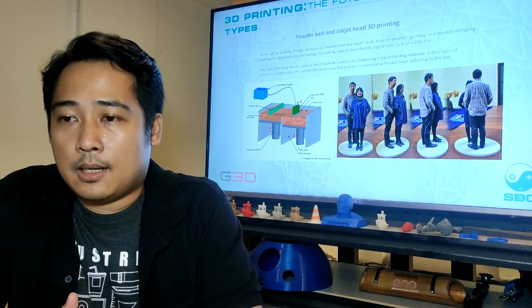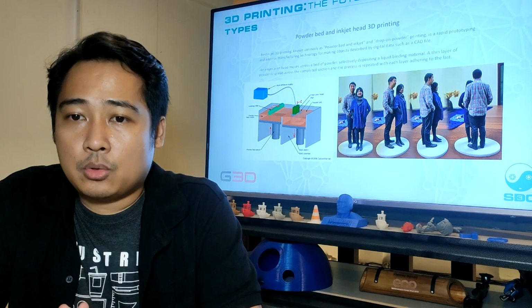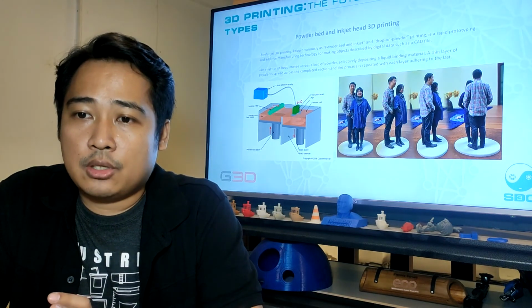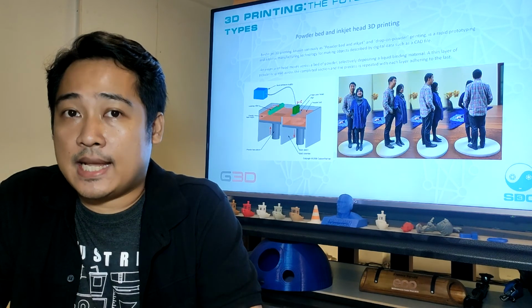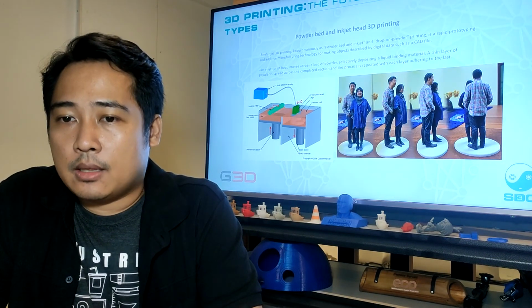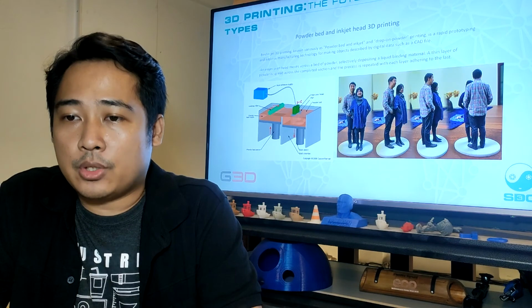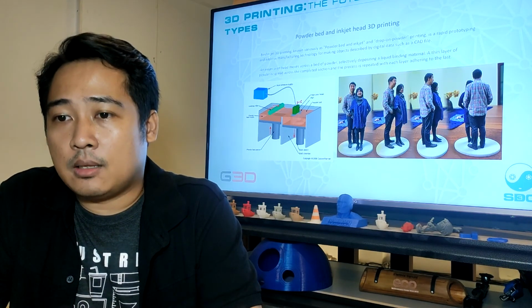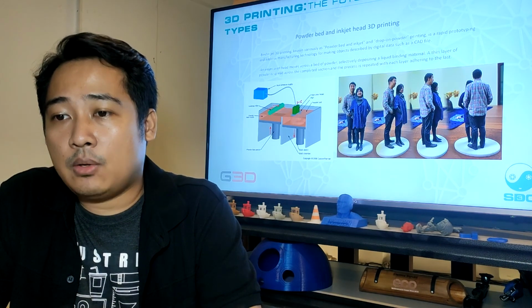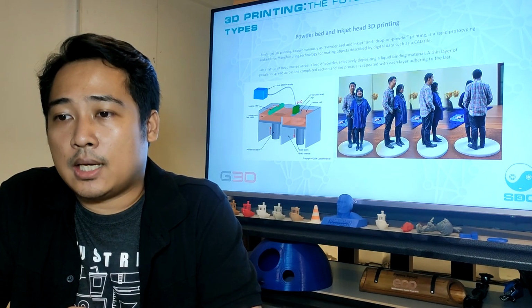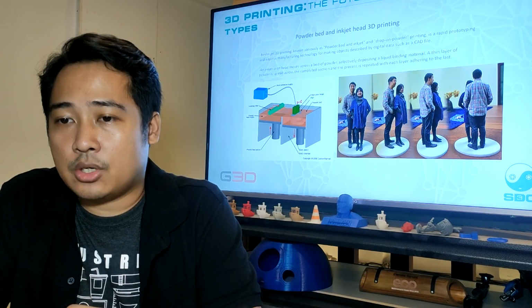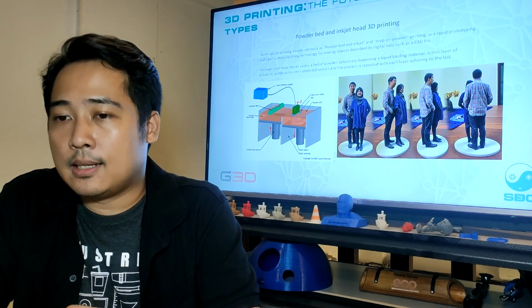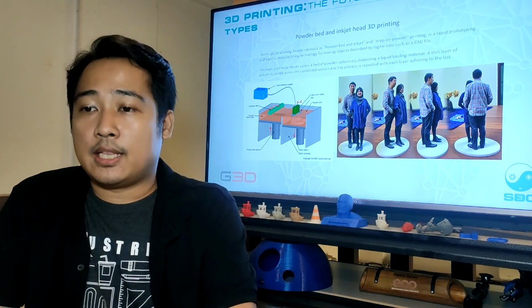It is a rapid prototyping and additive manufacturing technology for making objects described by digital data such as a CAD file. An inkjet print head moves across a bed of powder, selectively depositing a liquid binding material. A thin layer of powder is spread across the complete section and the process is repeated, with each layer adhering to the last.